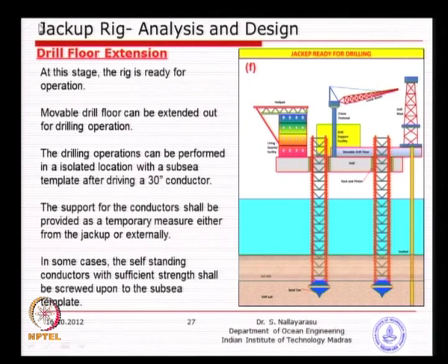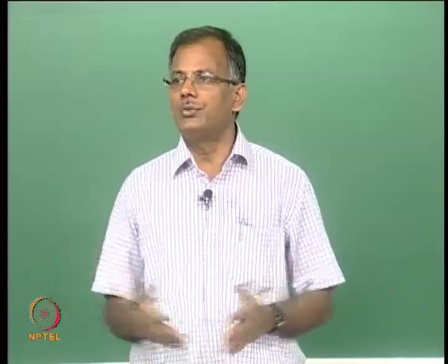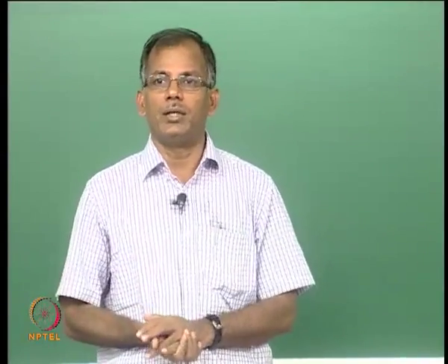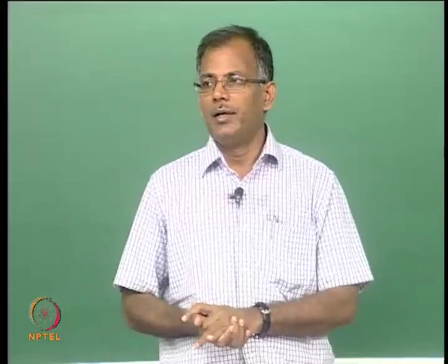The drill floor, I think, is a very important part of the jackup. Basically, this drill floor has two girders along this direction, large depth girders, which allow the floor to completely move together with the mast. This is the drill mast. Similarly, across the longitudinal girders, there will be two transverse girders, which will allow the drill mast to move perpendicular. So, you can position it anywhere and drill.